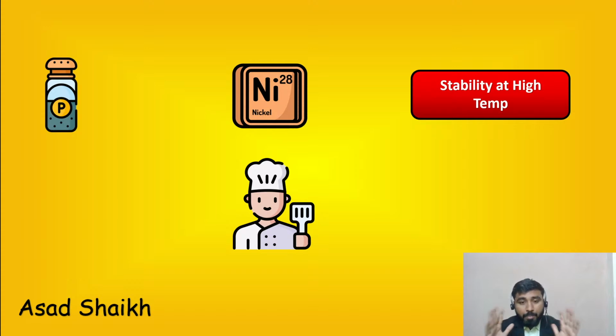But overall speaking, packing wise, low temperatures 200 degree, 250 degree, go for PTFE. If it goes to higher temperature, 400 degree, go for graphite. If you have fugitive emissions, you usually start with, first is V-type design, live loading design. If not possible, only then you start to go for bellows and those higher amount of packing. So based on your fugitive emission class, you can then go forward. That was one point which I saw had to be answered.